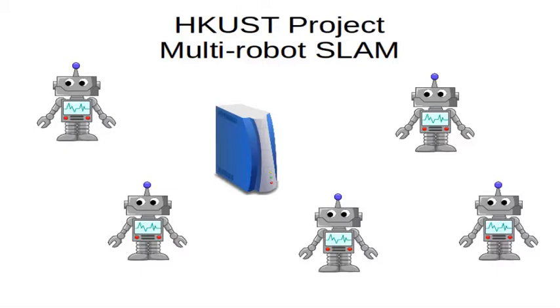However, a multi-robot SLAM system can usually be split up into two parts. One part is the slave robots, and the other part is the central computer. The slave robots usually move around, carry sensors, collect data, and may be very limited in computational power. The central computer usually has high computational power, can be stationary, or may not have any sensors.